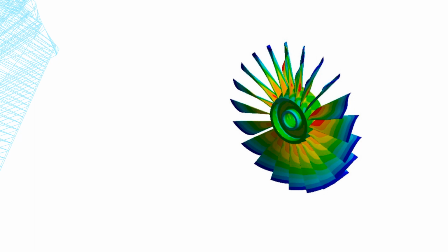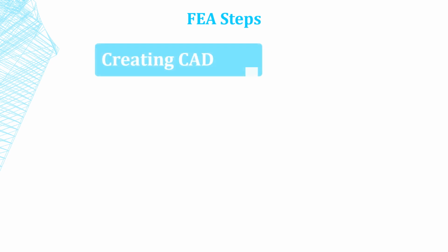Now you have got an idea of how FEA is useful to do strength calculations on complex geometries. Now let's understand FEA in more detail. Now let's have a look at different steps in FEA. Any FEA model starts with CAD geometry. Created geometry can be 1D, 2D or 3D depending upon the problem. After creating geometry, it needs to be divided into a number of elements. This is done in the meshing step.